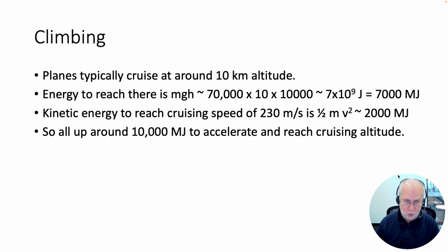So let's look at it. First of all, climbing. Planes typically cruise at about 10 kilometers altitude, so mgh is about 7,000 megajoules to get up there. Kinetic energy, half mv squared, is about 2,000 megajoules. So all in all, about 10,000 megajoules to accelerate and reach cruising altitude.